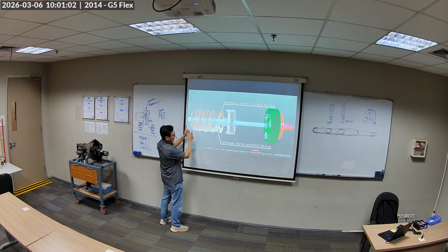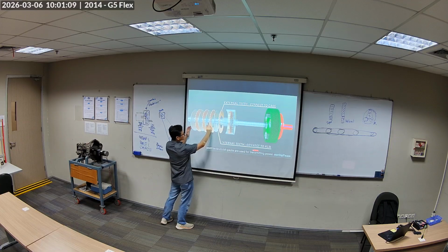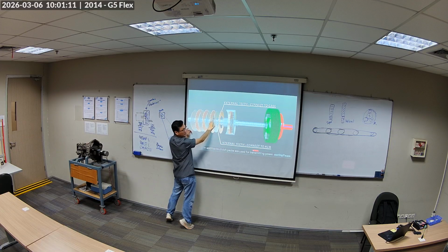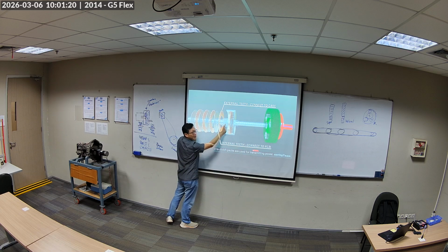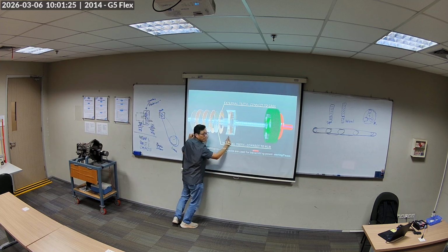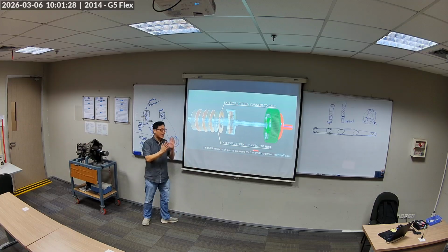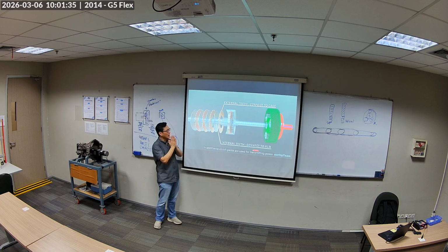Now, you have the gray plates and the bronze plates, right? The bronze plates have teeth on the outside. The gray plates, maybe you cannot see it, but the teeth are on the inside. So the gray plates rotate with the shaft. The bronze plates rotate with the hub. So when I press them together, they kind of float, each individually on their own.